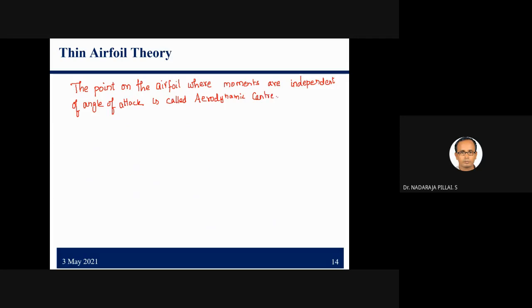But in the case of the center of pressure, all the resultant force acts there and also the aerodynamic moment is 0, right? So in the case of a symmetrical airfoil, both aerodynamic center and center of pressure are the same, right? At least theoretically we can say both are the same, right?